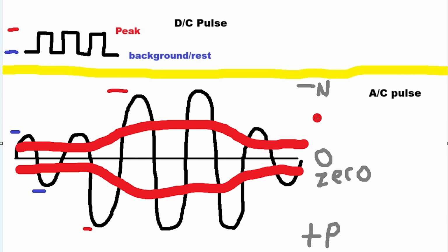And if you're going to do it, you want to keep the background current high. It's very common on TIG with DC to run 100, 150 amps on the high side and then say 30, 40 on the low, and you're not going to get cracking issues with that. On aluminum, you don't really want any more difference than maybe 20% from high to low, or you will risk getting cracks. And I'll even shoot a video demonstrating that in the future.